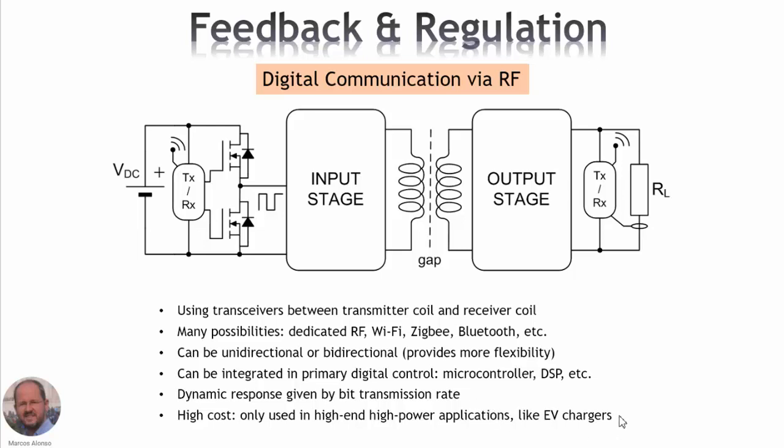And the main disadvantage of this solution is the high cost, because we need a transceiver at the input, another transceiver at the output. Usually we employ high-end integrated circuits like microcontrollers to implement these transceivers. So usually this is only employed in high-end, high-power applications, like for example in electric vehicle charging.